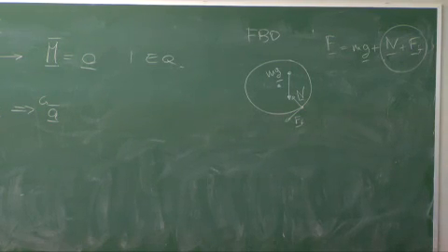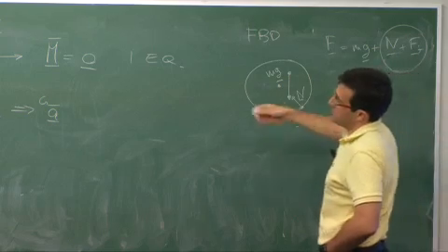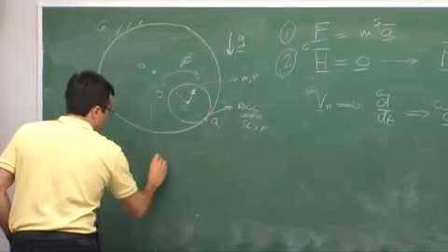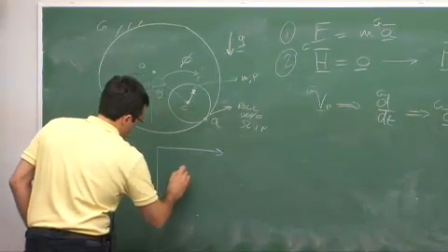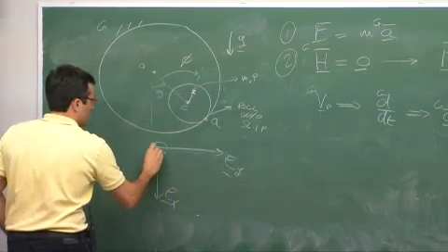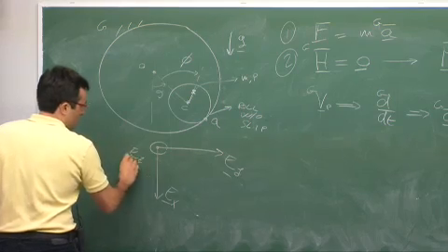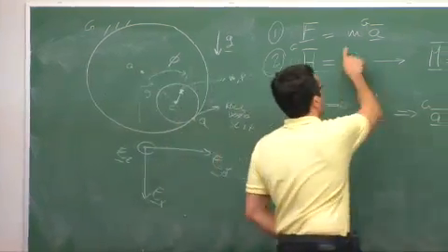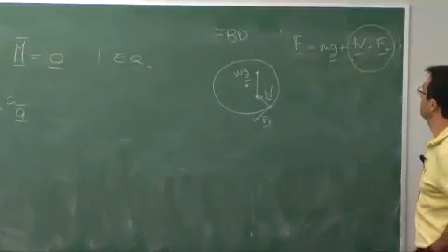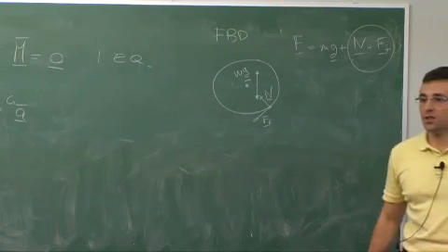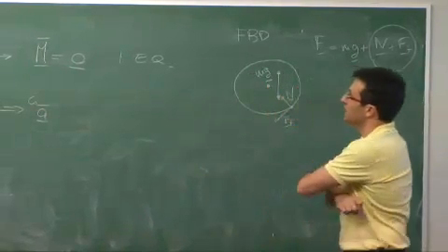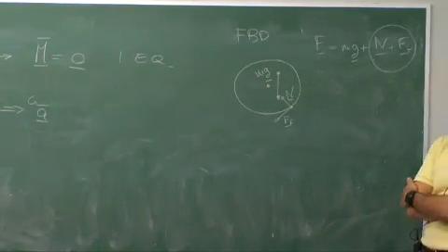I should get 2 equations, right? Because, well, this is a planar problem. So I believe we had some inertially fixed reference coordinate system here, which I honestly don't remember how it was ordered. I have it in my notes somewhere, something like this. So it's a planar problem, so I should have 2 equations from F equal ma bar G. 2 equations, 2 unknowns. Can I really get my differential equation of motion? Remember, these only required 1. You think I can eliminate both of them? I don't think so, right?